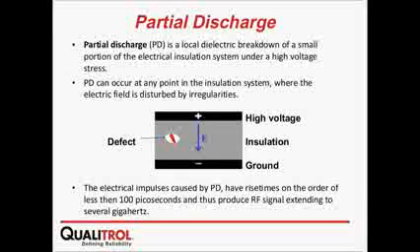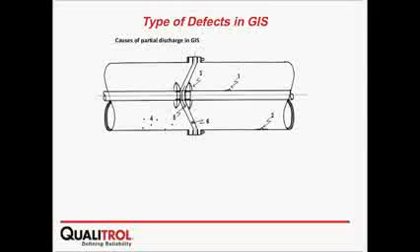So with an understanding of the partial discharge, we can focus on looking at the kinds of discharge that we have on the GIS, on the transformer, and on the breaker. So starting off on the GIS, we have a bus bar here with the live conductor in the center, barrier insulator, and with 6 types of defects.